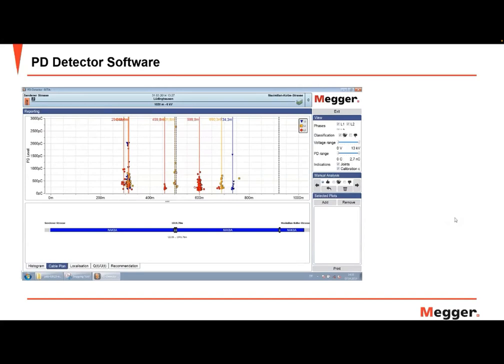In a situation like this, as I go right back to the cable clamping, if those cables were clamped and over torqued, then you can cause inhomogeneous distribution of field and cause PD activity to take place. And it was done on all 3 phases. So this is something that could be representative of a condition like that, where you may cause a defect by over torquing your cable.